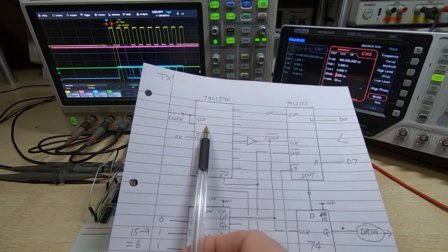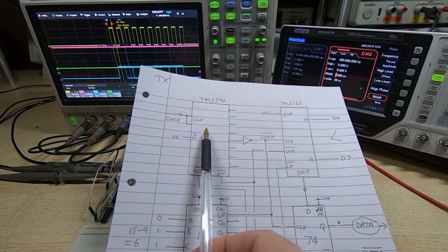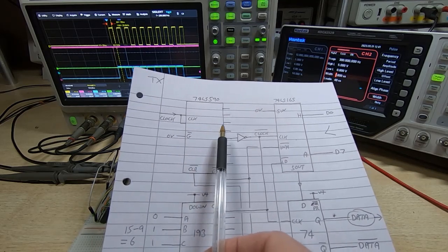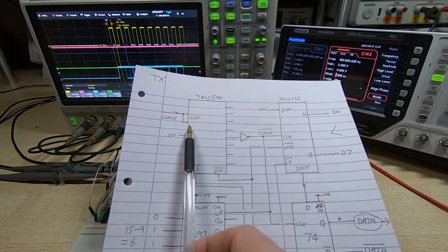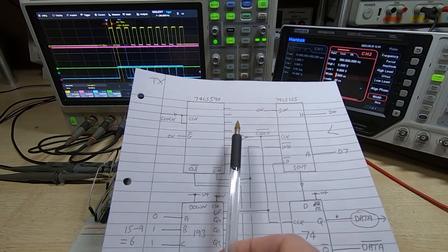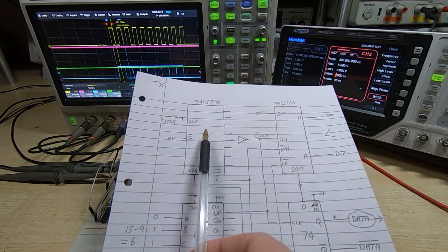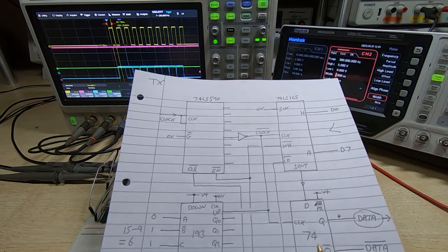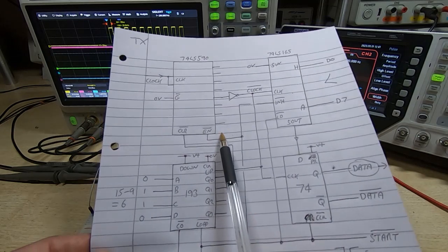One is the clock input for the counter, and it increments the counter. The other clock is to latch the data that's come out of the counter into the register, and it's the register that feeds data to the output pins. But this arrangement means that if you clock these two together, then the output from the pins on the device are always one count behind the value in the internal counter. Now when you're going round and round, it doesn't really matter. The clock phase is not that important, but where it becomes an issue is when we reset this.